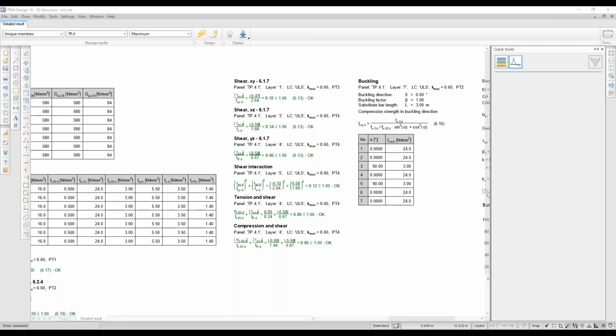And then the next design criteria doesn't have a Eurocode reference. So this is where we have extended the checking procedure outside of the regular standard. The reason for this is, as previously mentioned, that CLT is not fully covered in today's Eurocode 5. It's not an individual material and it's not fully standardized. So that's why we have additional optional checks, which are basic conservative strength of material checks.